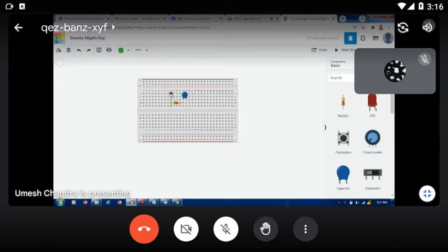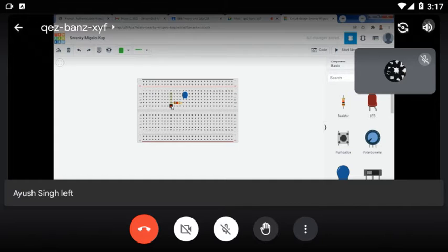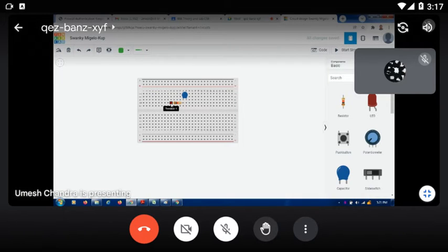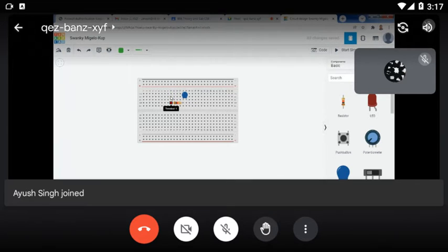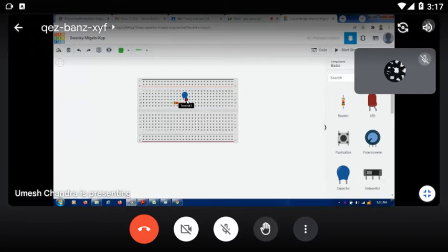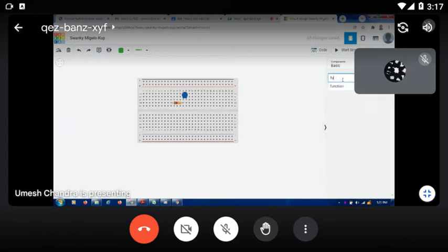Now your input is at this point. Input terminal number 1, and this side is terminal number 2 of the resistor. Your input is given to terminal number 1 of the resistor, and all these holes are terminal number 1 of the resistor, and this side is terminal number 2 of the capacitor. Then the negative is given to terminal 2 of the capacitor. So now I take one function generator. You write here function generator.